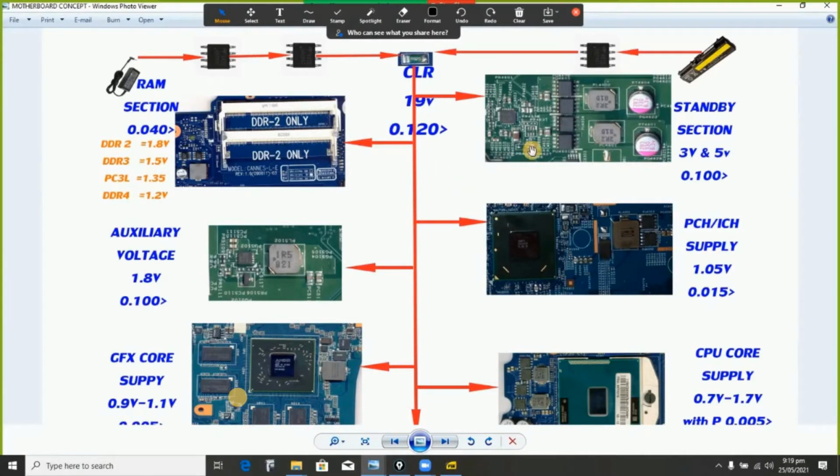So this is the point where they both communicate as to how they are going to power the system. For every other part of this system to work, after this 19 volt is present, if it is battery, we have approximately 11.5, 12 volts. Let's just say 12 volts. We won't place attention on that now, because with test runs we troubleshoot laptops with the charger. So we'll be talking from the perspective of the charger.